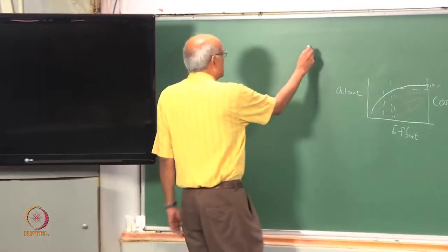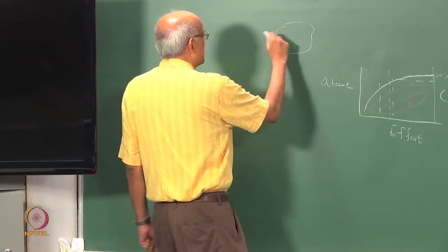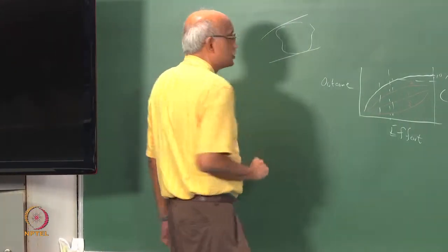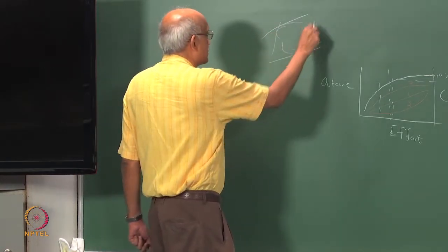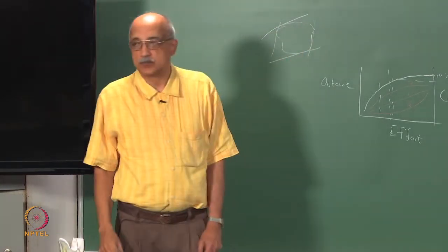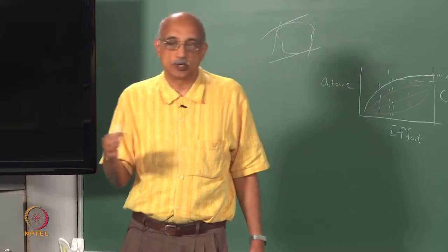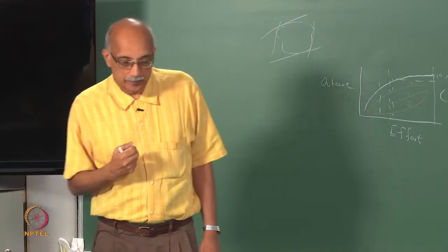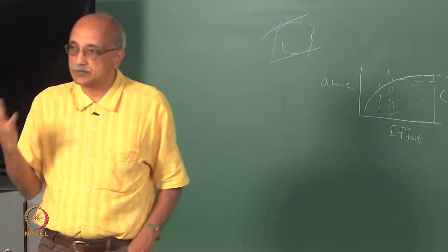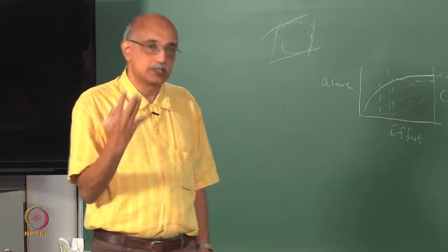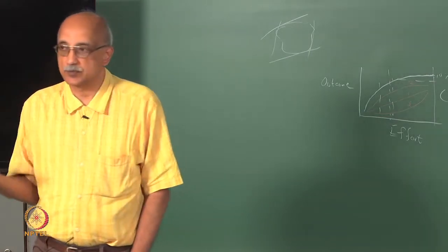So, if you have a particle that looks like this, you would draw 2 tangents here and measure the distance between them. You will draw a couple of tangents here, measure the distance between them, and you keep doing this over and over until you develop sufficient confidence in your data that you have captured all the essential features of the shape of the particle.